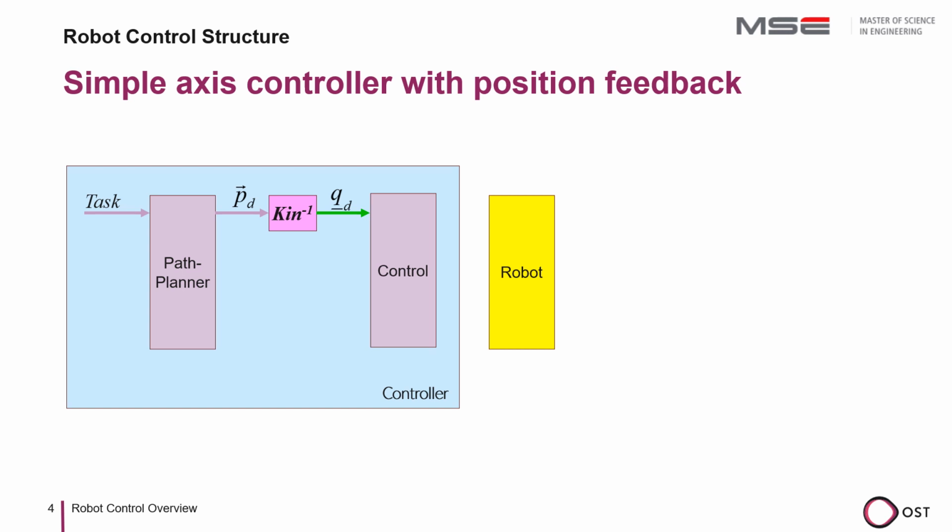The robot has joint sensors with which it determines the current position. This position is also represented in generalized robot coordinates. We usually indicate actual values by not using any index. The controller compares the set point and actual positions, uses them to calculate the positioning forces represented by the mathematical vector Q, and controls the robot's motors accordingly.